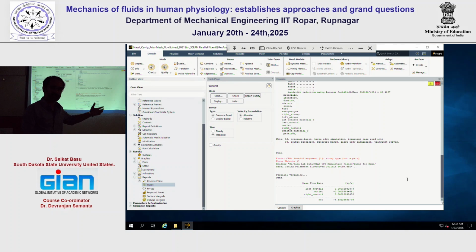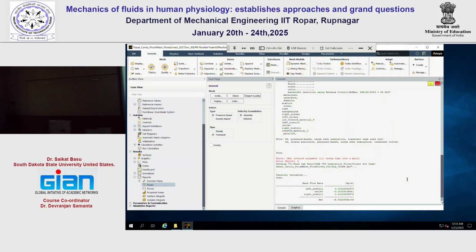Then you might have to redo the simulation, make sure that the pressure values get changed a little bit, and you can also do an interpolation study: run two simulations, figure out which pressure values led to what flow rate, and then interpolate to figure out at what rough value of the pressure drop we would get a 30 liters per minute flow. But we got lucky here, and many times we do get lucky, and we got an outlet flux that is 30 liters per minute. So you should save this particular window every time you do this kind of work.